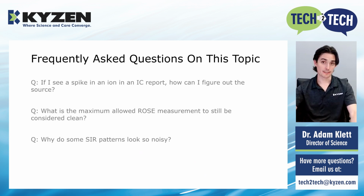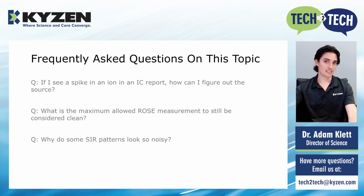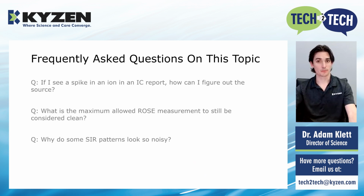All right, the second question that I frequently get asked is, what's the maximum allowed ROSE measurement to still be considered clean? Well, the IPC recently changed their stance on this, and there is no longer a universal number to indicate clean. Your boards must be shown to be clean using a different technique, like SIR, and then correlated back to the ROSE data. A process that has been qualified can be monitored using SPC techniques and the upper and lower limits will be defined during that process.